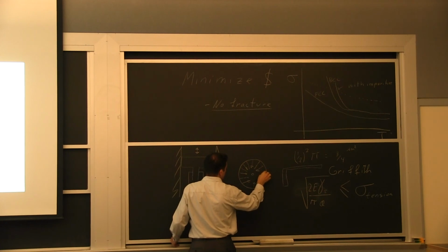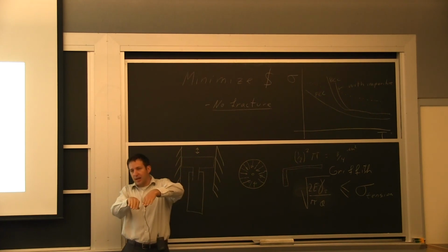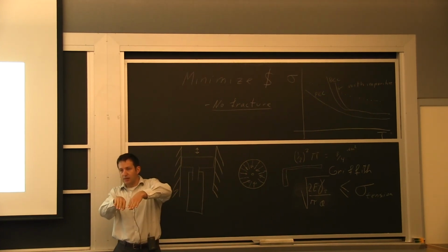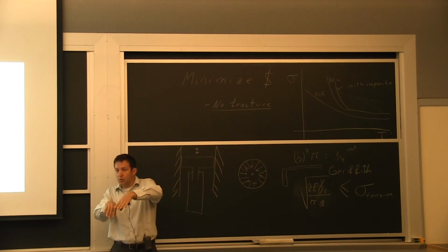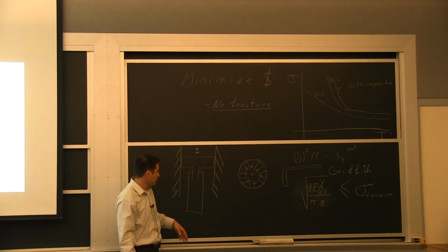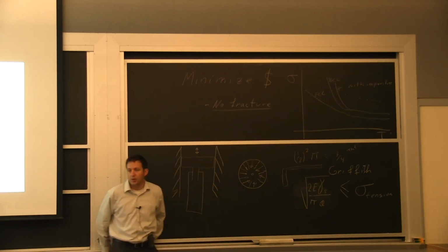The ridges, most of the time, just separate two cracks that were not exactly on the same plane. So they show you the step to go from one crack to the other. And most of the time, the overall crack propagation direction is parallel to these crack propagation lines.